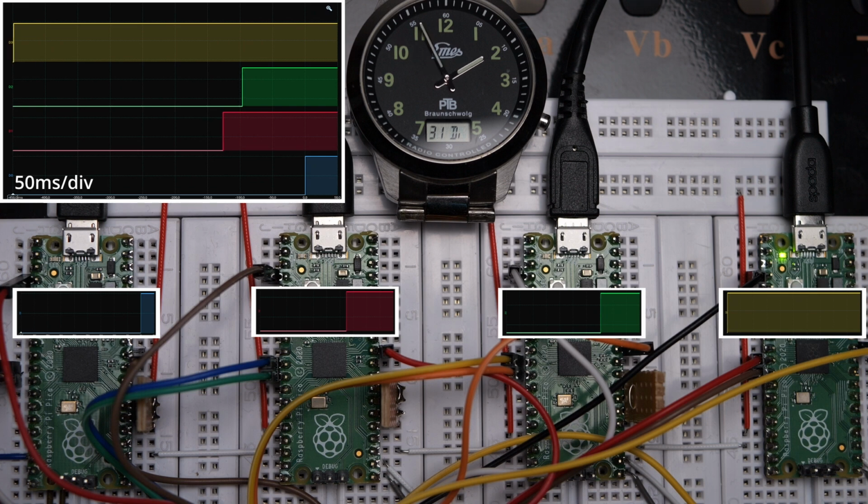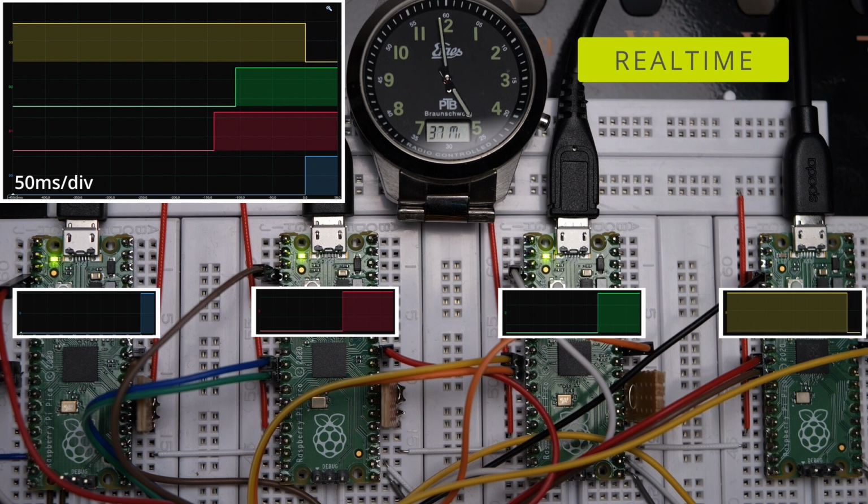30 hours. The yellow LED on event has left the logic analyzer buffer, and the yellow LED off event is right on top of the blue LED on event. Rightmost and leftmost Pico are now flashing inverted patterns. One is on when the other is off.